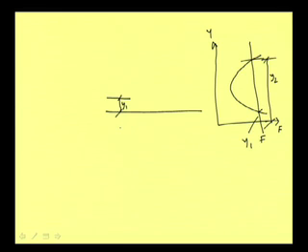Now, if we fix this depth y1, we know that this is supercritical flow, and at the tailwater, that is the downstream side, this depth must be subcritical. Then only a hydraulic jump will form. Otherwise, if on the downstream we also have supercritical flow, there will not be a hydraulic jump. There will be a gradually varied flow profile in that case.